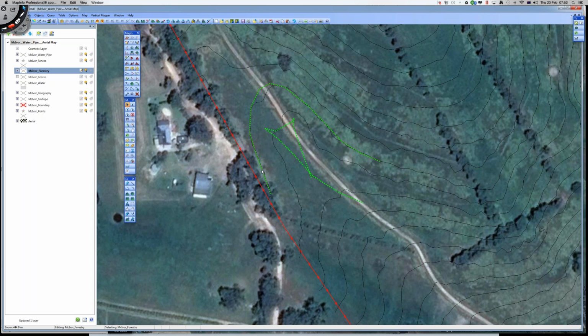Now see what it just did then? Wow. Let's try something else. I'll just hold that thought. Let's do a 10 meter parallel. Go right again. Now see how that keeps. But look at, this is a useful function here. What you'll do when you're using parallel offsets, you'll use this key all the time. It's the reshape key or tool. The reshape key shows you when you're clicking, you're putting out a series of nodes.